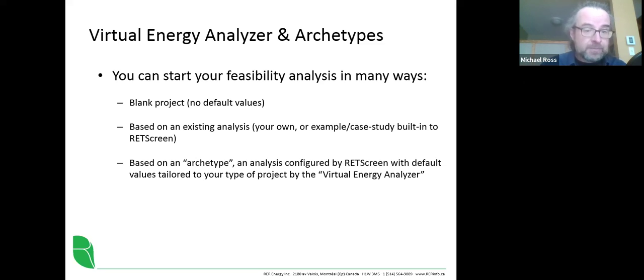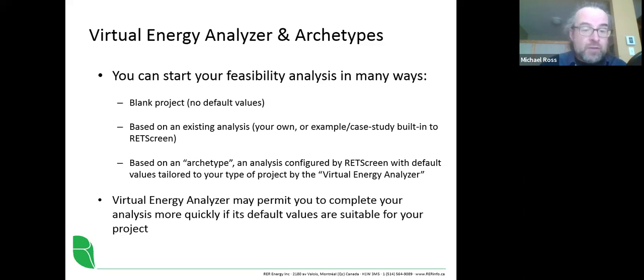The third way is based on an archetype. So that's an analysis configured by RETScreen with default values that are tailored to your type of project. And that's done by this so-called virtual energy analyzer, and we're going to show that today as well. So the virtual energy analyzer may permit you to complete your analysis more quickly where its default values are suitable for your project. So that can be of interest.